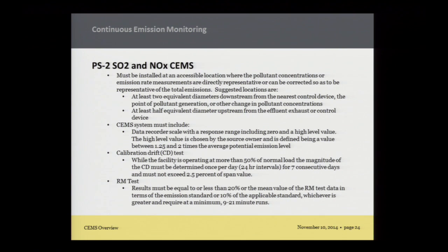So when we stack tested, we typically suggested to do 12 just to be safe. You can throw 3 out, you get your 9. Some places are comfortable doing 9, but if you end up with a bad data point, you don't get to throw it out, and you could fail your RATA, and then you're doing the whole thing again. Whereas if you had done one more run, you may be good. Yep.